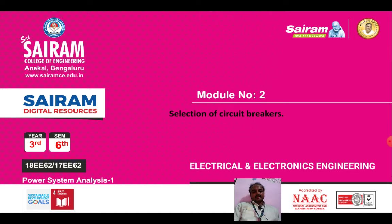Once fault current comes, once heavy current flows to the circuit more than the rated current, the fuse element will get heated and it will melt, so it will isolate the fault. Similarly, the fuse can give fire hazards, but a circuit breaker will not give a fire hazard.